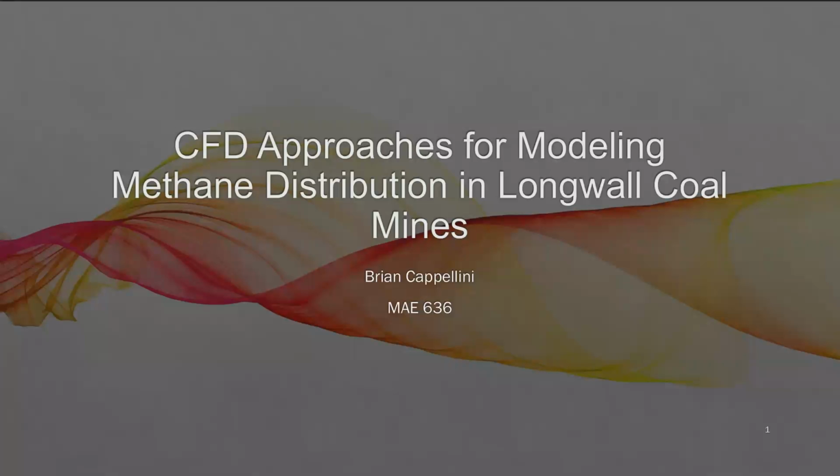I'm specifically looking at modeling that methane release that we're discussing as a product of coal, and we're trying to predict what those concentration profiles may be downwind so that we can test the effectiveness of this system that Amber had previously described.